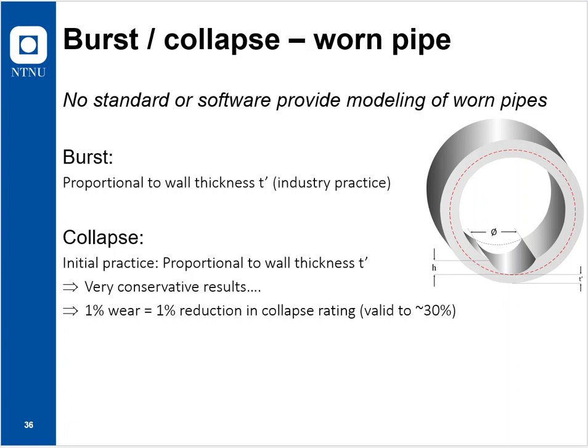And the places where you would not have much contact would typically be close to the neutral point, and then in the compression again, with a significant portion of compression, you would find that there's a contact on the outer curve of the well bore, yeah, or casing for that matter.